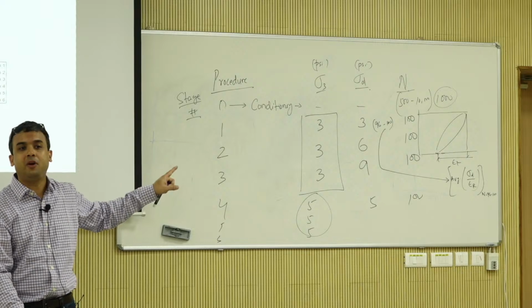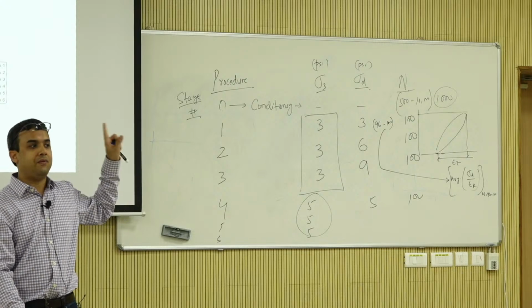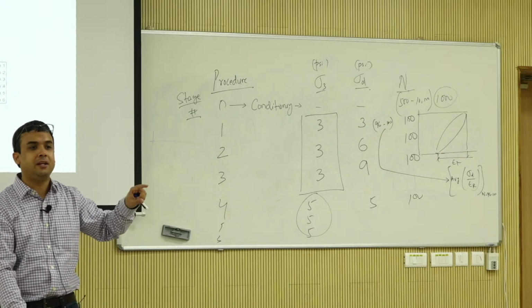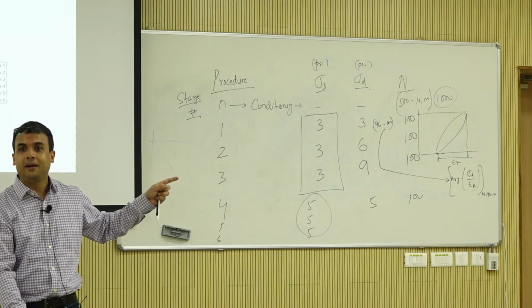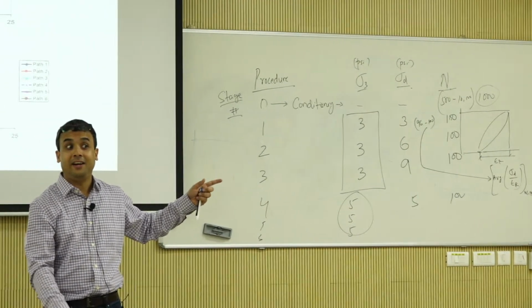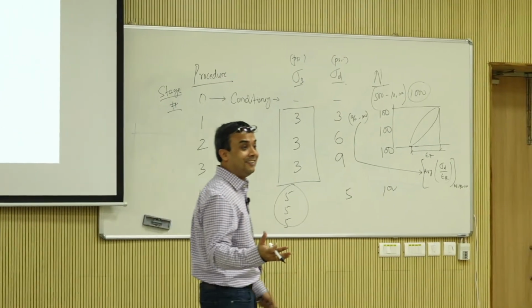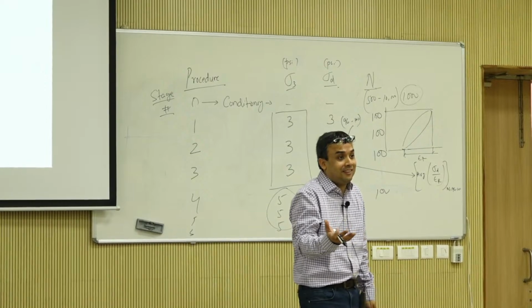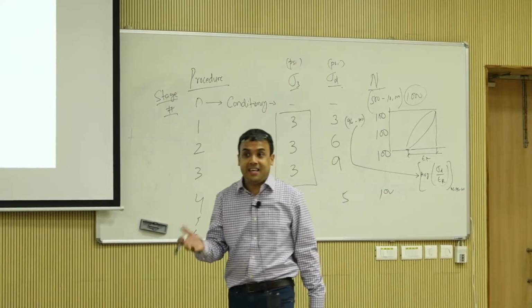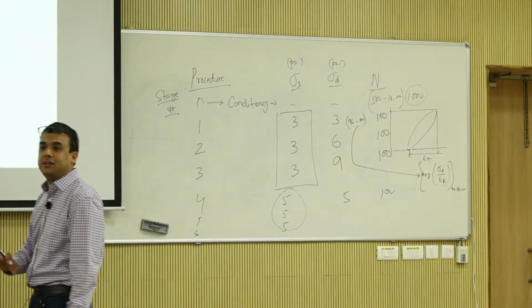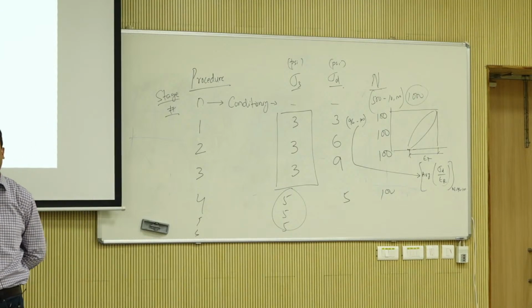How many sequences are there? So how many resilient modulus values are there? So if I ask you what is the resilient modulus of this material, what do you say? It depends. Tell me the stress state. What stress state is it? Right? E is equal to 30 ksi or 30,000 psi.